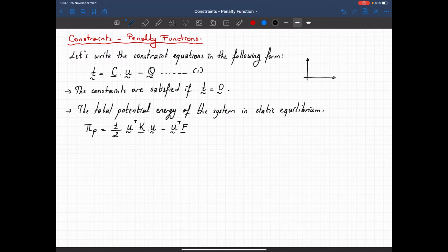So this is the internal energy, and that's the displacement. And we see a relationship like that, right? And the magnitude of that is equal to K times U. I'm just doing it for a single degree of freedom system. And the strain energy is the area under this triangle, which is 1 over 2 times K times U squared, right? So I just write the same thing for a multi-degree of freedom system. That's the internal strain energy. And this is the work done by the external forces.